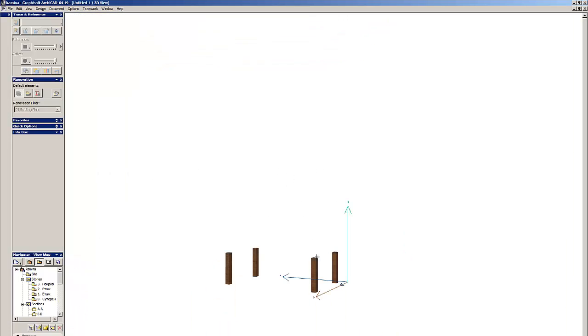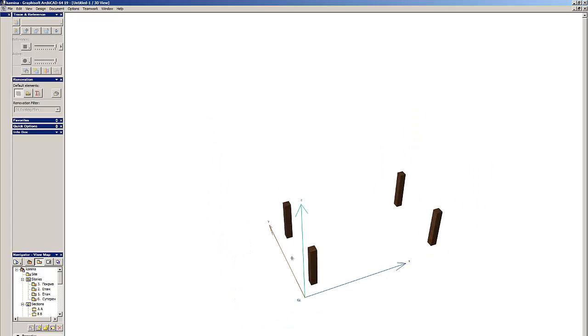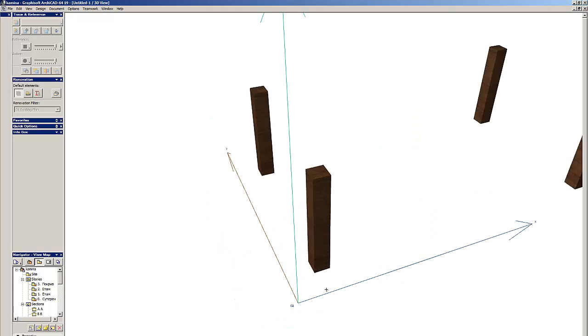3D view. Here we are. We started here, as I said, in the bottom left corner. The x-axis is the length and the y-axis is the width. And it inserted our legs based on our L off distance, which is 10 centimeters. These two distances are 10 centimeters. First I moved it 10 centimeters along the x and 10 centimeters along the y-axis. Then I moved it 10 centimeters along the x and the whole depth minus 10 minus the leg width, and so on.